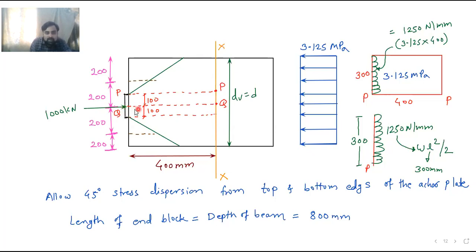Okay, so we consider that from the centroid line, for the above portion, half of the pre-stressing force is there. For the below portion of this centroid up to the anchor plate, half of the pre-stressing force is there. Now for this topmost half portion, we will consider the average pre-stressing force, and that is P by 2.